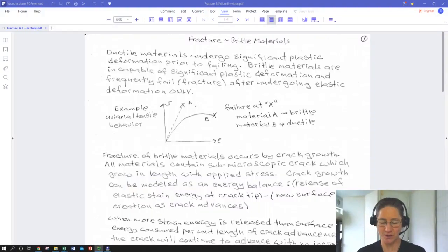In this lecture we're going to expand the concepts that we've established about yield criteria, especially with Tresca, to looking at what happens when we have to be concerned with fracture. So in our discussions about yield criteria, we established that materials yield based on applied shear stress. So it was really important that we understand either what the max shear was if we're going to apply Tresca, or kind of its strain energy analog, the deviatoric strain energy that was going into things changing shape.